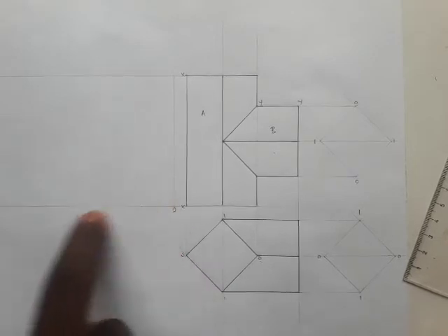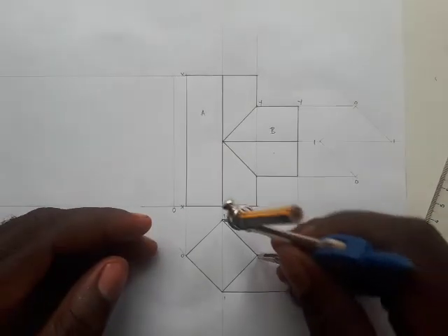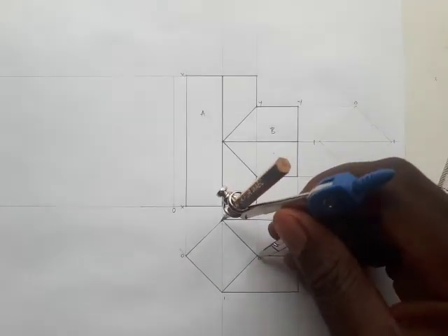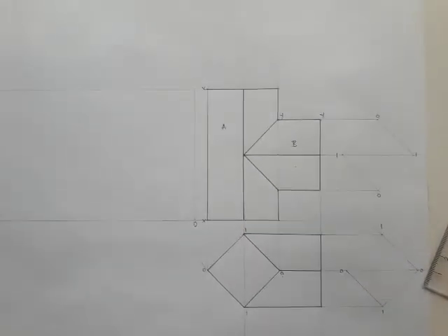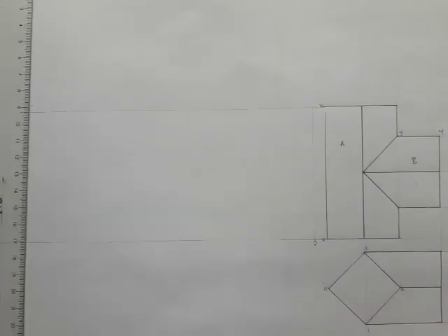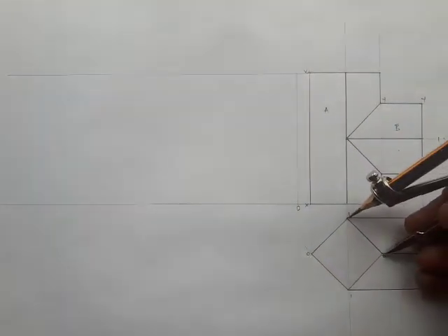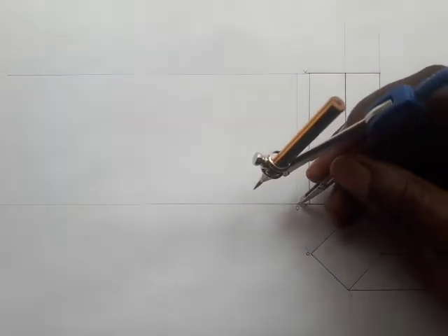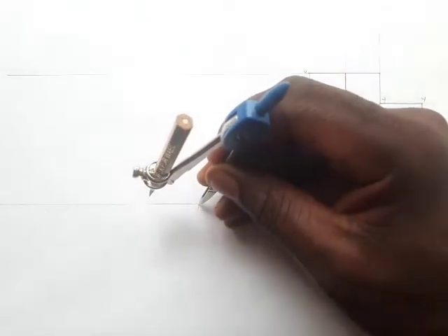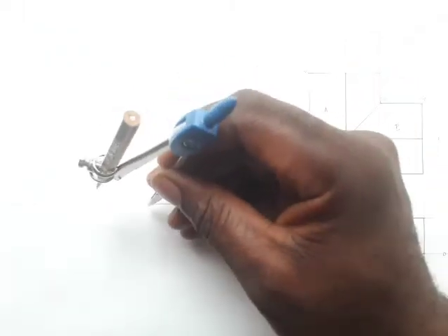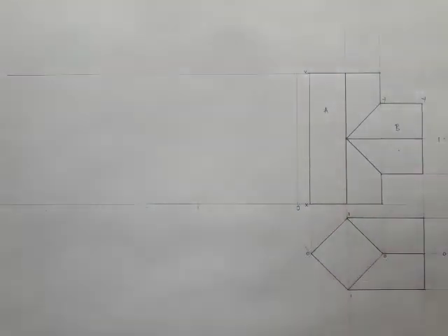Okay, so we're going to what? Stretch any of these distances. That is 30, I guess. Yes, the square is 30, so stretch 30. And let me adjust this. Good. Stretch 30. So with this 30 you've stretched, or just this length, you needle and step off 4. 1, 2, 3, and 4. The reason we are stepping off 4 is because the square has 4 equal sides.